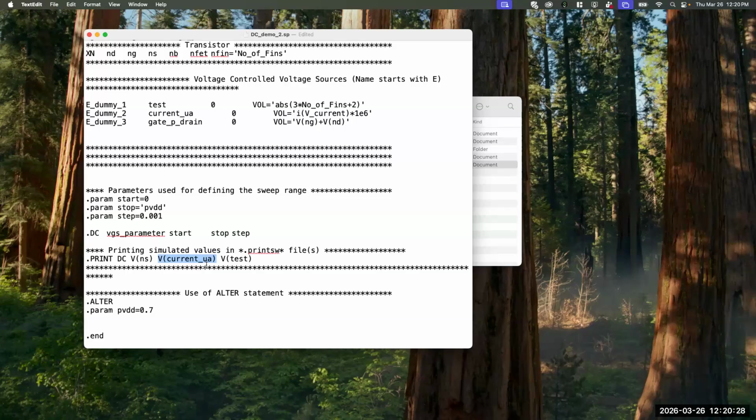And I told you a story from my life. I'm not showing you anything that I haven't done myself. So in Global Foundry, for example, they had a bunch of data every weekend. And next Monday, I was at a loss. Like, how do I handle all of this? So I wrote a MATLAB code that used to run the HSPICE code, get all the data, automatically import them, and then plot them in different figures.